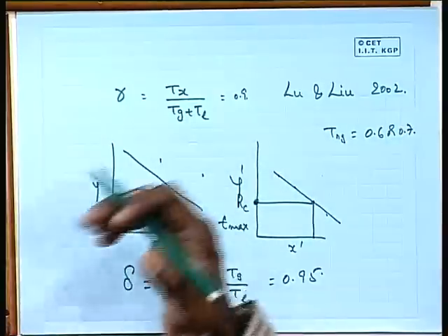So without going into a number of experiments for that alloy, one can just read from such a plot, but for that your plot should be reliable. That means the correlation factor for that plot should be as high as possible, so that the parameter which represents the glass forming ability of various alloys can be a reliable parameter.